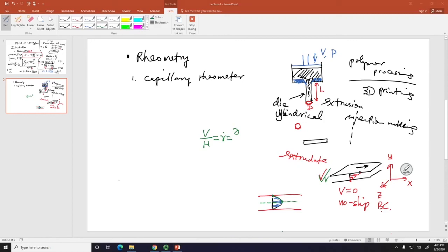But if you want to get even slightly fancy, if you allow me to use calculus, what you have is really this: a velocity in the x direction that is changing with y. And since it's a simple shear, there are no other velocity components, so I don't even need a partial derivative. I can just use the total derivative.